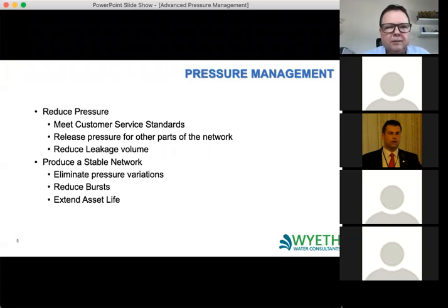Unfortunately, these days, monitoring of transients is not something which is done too much by water utilities. And a lot of water utilities don't realize the sort of transients that they have in their network. If you're logging at, say, 5-minute, 10-minute, or 15-minute intervals for your pressures, you're not really going to be picking up any transients. You really need to be logging at sub-second intervals, often 128 times per second or 256 times per second, to get a real visual of what the transients are doing.